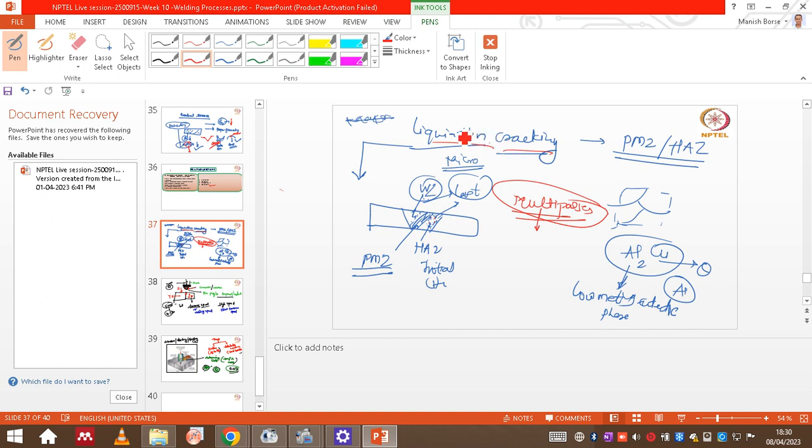Let's say the solidification crack is sometimes visually, macroscopically visible, and obviously as the liquid film is torn apart, it will have smooth interfaces, and it will generally happen in the fusion zone, right? Because that's the last solidifying region.